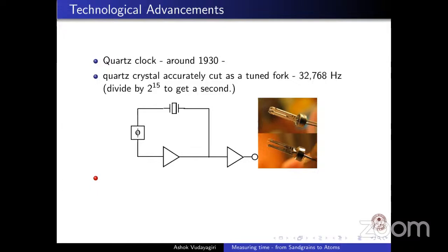So when you measure 10 oscillations in a second, your error is 1/10 of a second. If you have 300 oscillations in a second, then your error is 1 over 300 second. So your error becomes smaller and smaller. For a quartz clock, my error is 1 over 32,768. That's a very small error, and that's why now all of our watches have quartz clocks. Another biggest advantage the quartz clocks made was making it very compact. I have a quartz crystal oscillator inside your mobile, in watches, in a pen, inside my laptop, everywhere. All of them keep time.